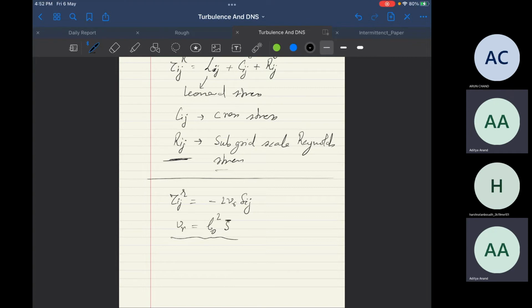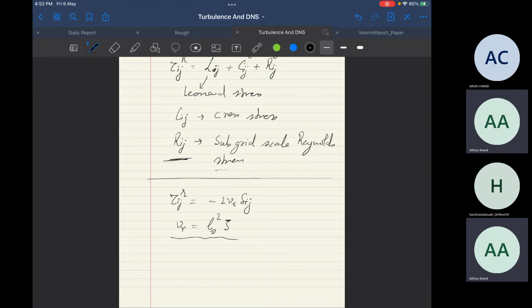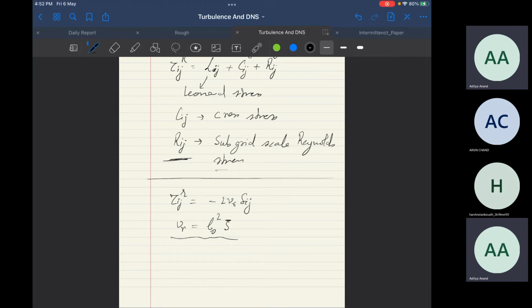There could be magneto-hydrodynamic forces, but I think in those cases you cannot include those terms in pressure, and you'll have to consider their effect as well. You'll have to solve for those. I don't think there is a way around that. So let's say at small scales we have surface tension forces. We do not include those in pressure. Definitely, if we have an additional pressure, we have to consider that.